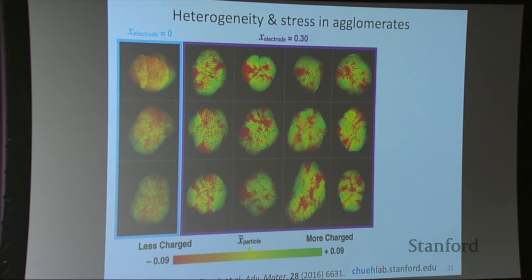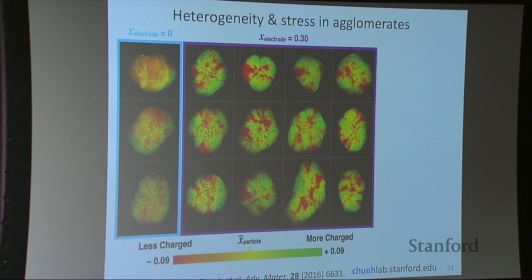There is a coupling between the voltage locally and the mechanical stress. When you have a different mechanical stress state, you have a different voltage. If you have a different voltage, a different open circuit potential, those are going to be the spots that get charged first. In fact, you get this pattern because the system is trying to maintain a constant potential. Just like a balloon, if you squeeze a balloon, the air goes somewhere else. That's exactly what you're seeing here. You squeeze part of the balloon, the lithium goes somewhere else. And this gives a very interesting coupling.